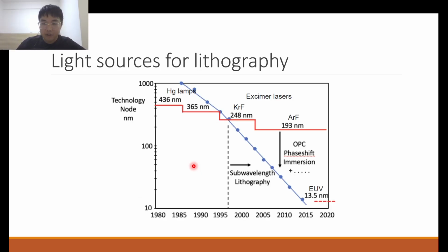So for a photolithography machine, we do need a light source. We need a source of the UV light. So what has been the trend over the years is to get light sources of smaller and smaller wavelength of the UV radiation. Why is that? You'll see later, but basically a smaller and smaller wavelength is able to result in a better and better resolution. So resolution is like your photo resolution. It's how small your features can get without being too blurry, right? So of course, if you can get better resolution, you can get sharper features, and sharper features means you can get smaller features that you can define on your wafer, and that normally can result in the formation of more advanced devices that have better performance.